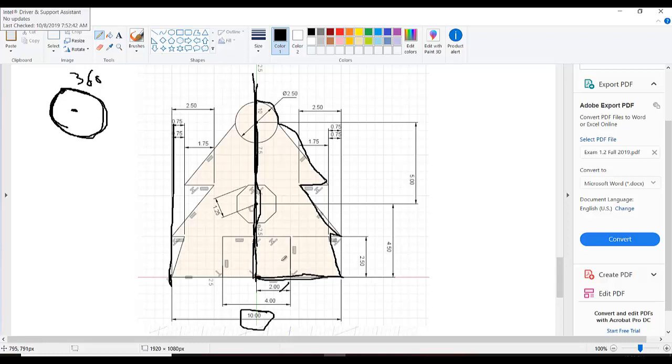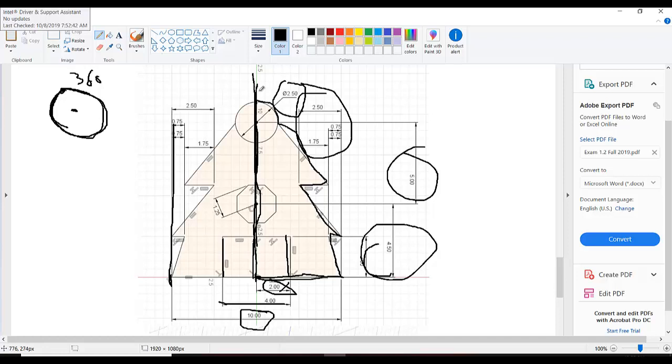So for here to this point we need to define the dimension of 2 centimeters, and this is the full dimension from here to here, but we need 2. But all the other dimensions we need the same, because these are not around this axis which we are going to use to revolve the sketch.